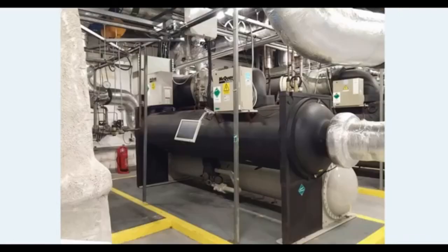And if we look at the back of this chiller, there's the condenser again there, and you'll see this tube, this pipe coming along from there and entering into this black box. It's covered in insulation. This is all insulation, by the way, because that chilled water costs quite a lot of money to produce, so you want to retain as much coolant into that water as possible. So that is entering into the expansion valve, which expands the refrigerant and allows the refrigerant, when it enters here into the